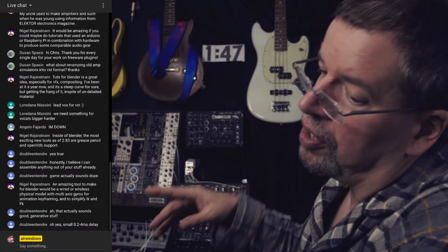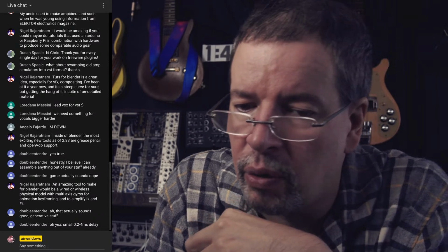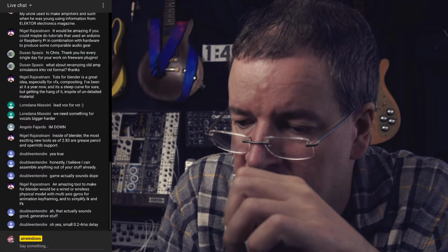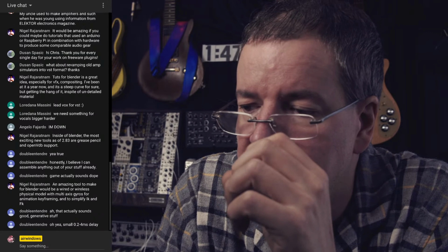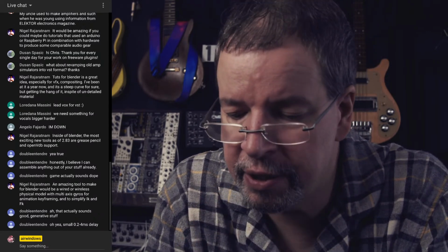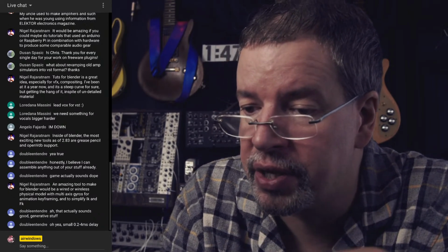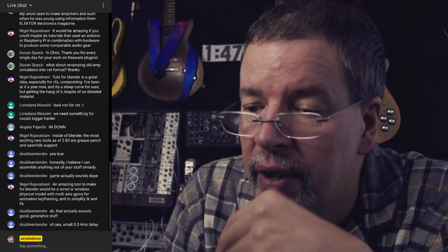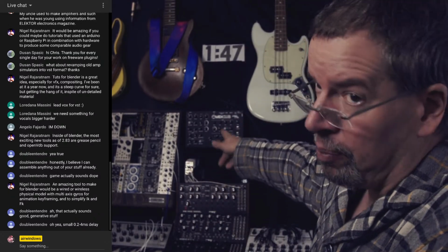And if lots of the notes are on, it will produce a digital word that becomes, there's another chip which I actually have some of. It's a DAC 800, a simple 8-bit DAC for taking the output of one of these things and giving us an analog voltage relative to what would be interpreted as a number. And that's what the out is on these, that chip producing the output.